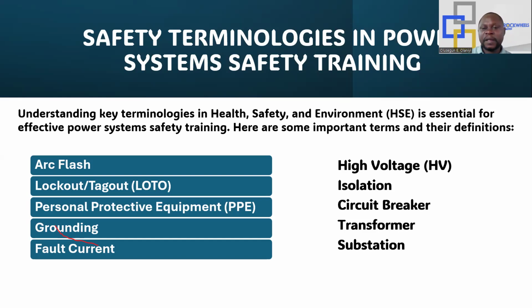Now, what that simply means is the ability for you to close a particular, let me give an instance. Let's assume you want to start an equipment or carry out maintenance of an equipment. So you go to your changeover and disconnect the power supply in that distribution line. When you disengage it with the changeover, you use something to lock it such that another person will not come and say, why is there no light here? And the person puts it on.